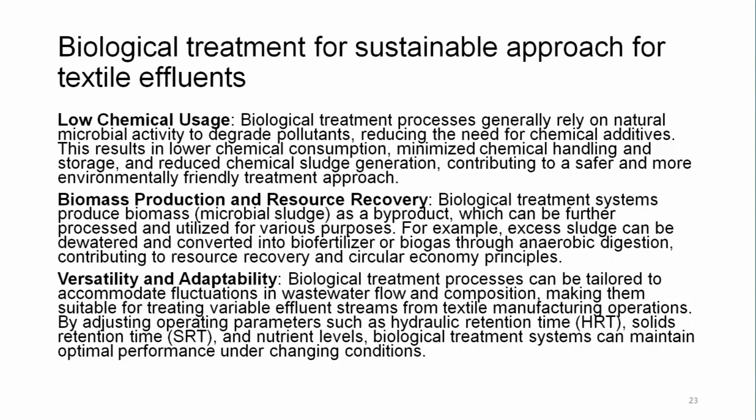Versatility and adaptability. Biological treatment processes can be tailored to accommodate fluctuations in wastewater flow and composition, making them suitable for treating variable effluent streams from textile manufacturing operations by adjusting operating parameters such as hydraulic retention time, that is HRT, solid retention time SRT and nutrient levels.